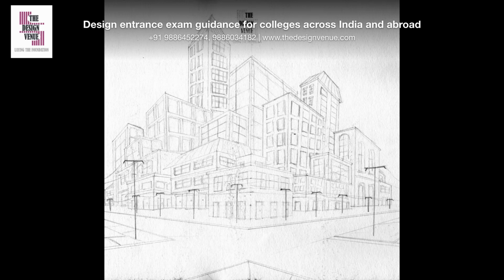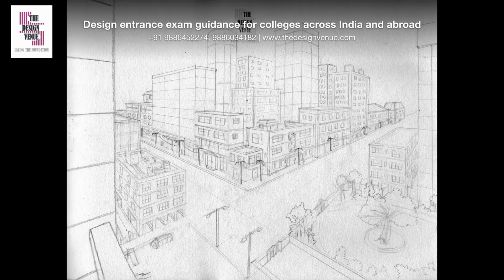You can start practicing 2-point perspective through drawings like this. In this drawing, the viewer is at the height of 6 floors, which is basically 60 feet from the ground. And you can use the 10 feet wall reference and 6 times that measurement, and you will get a reference of where to place the vanishing points. This view is also comparable to that of the bird's eye view.